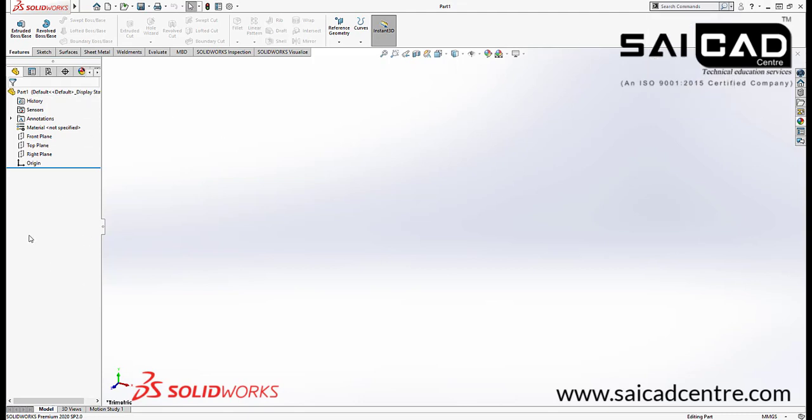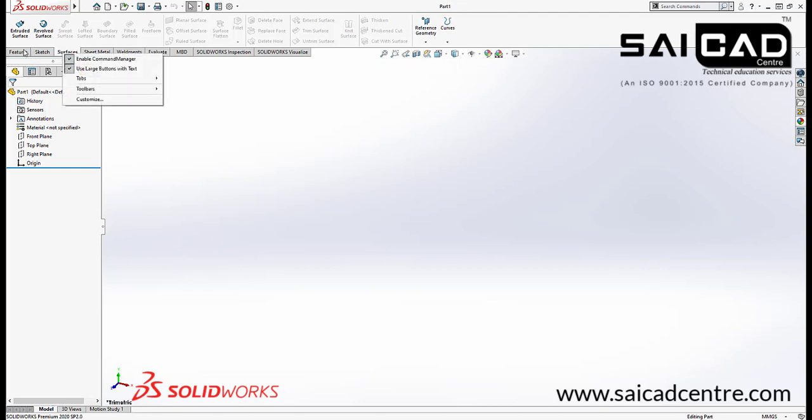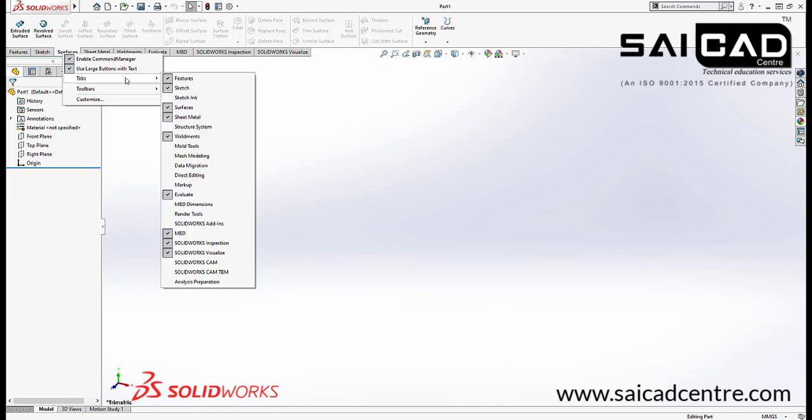Then we have the model tree here and the ribbon bar. In the ribbon bar you will get the tabs. For solid modeling we have the Feature tab here. For sketching we have the Sketch tab. For surface modeling we have the Surface tab here. If you don't see your required tools here, just right click on any tab, go to Tabs, and you can activate your tab from here.